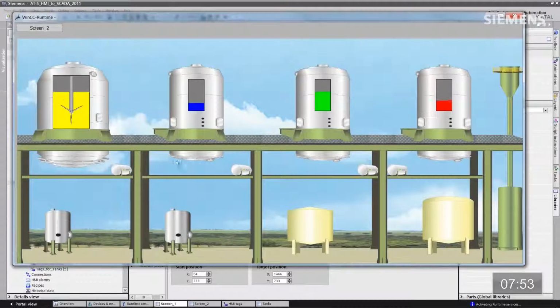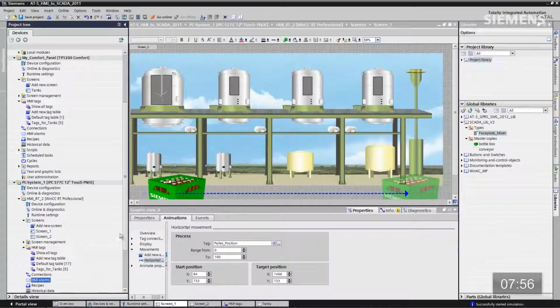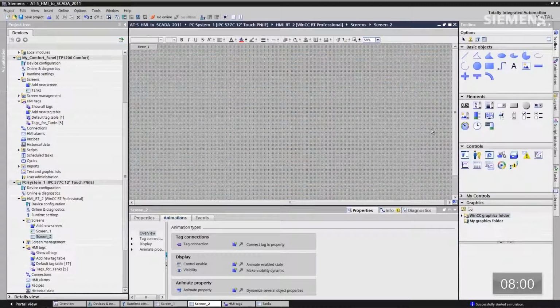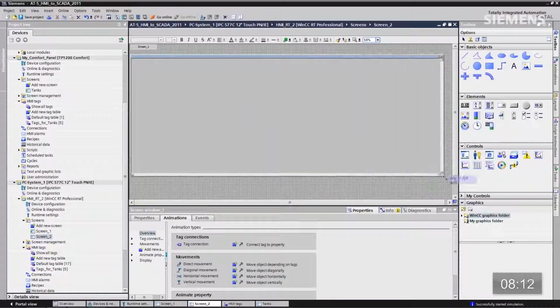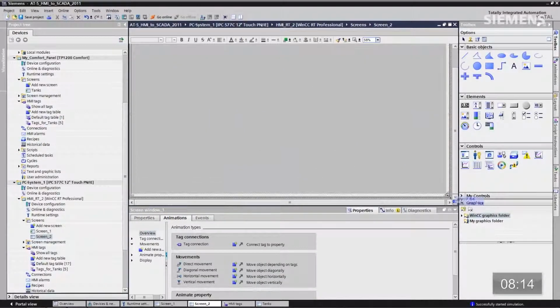However, there's one other thing I want to show you. How about actually doing a screen-in-screen or pop-up technology? So let's go to screen 2 real quick. Double click on it, and let's go grab the control icon for this. It's called Screen Window. Let's drag it on. This is the ActiveX control. You can see a little alignment bars just like in PowerPoint. That way you can align your boxes wherever you want to and get everything sized right. Let's resize, refit them onto the screen.